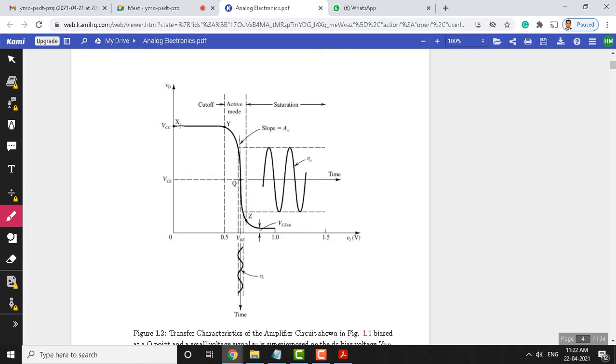You can see it is a straight line here, perfectly horizontal, parallel to the x-axis, and even for higher input voltage, it is again very close to the input signal. Overall, the transfer function is non-linear. So now the question is how do you use this for linear amplification?